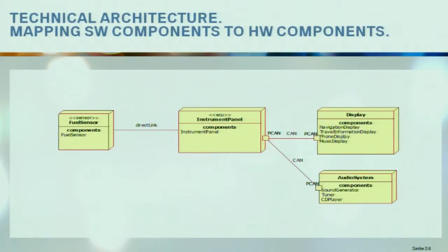Now you have to map and bring this software to hardware, and that's exactly done here. You think about connections which are directly linked, which go through buses, and you more or less partition on different things like ECU load and timing issues between the software components about the partitioning.